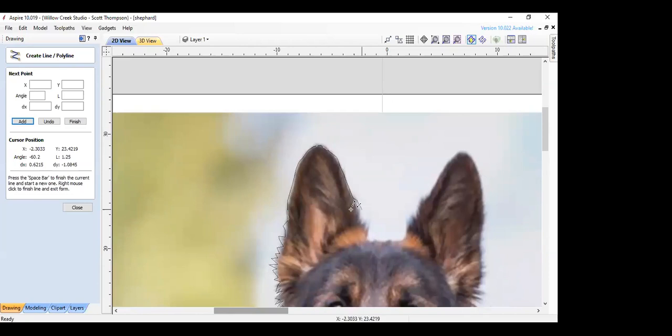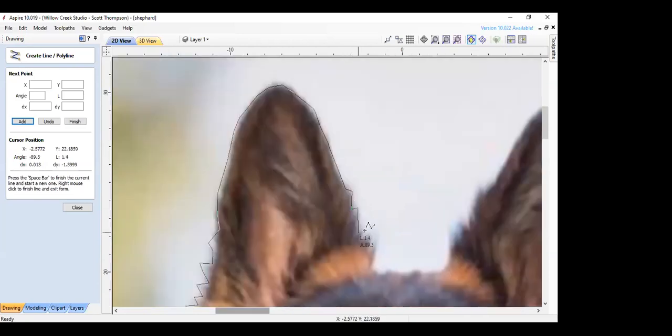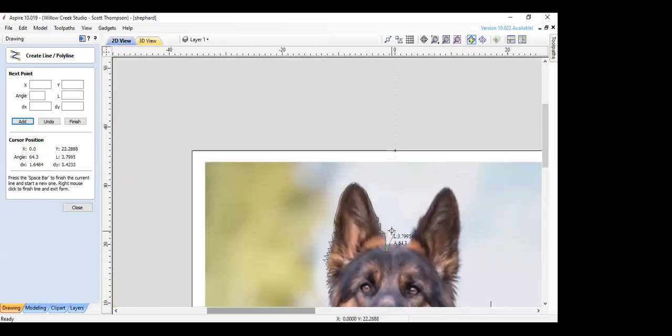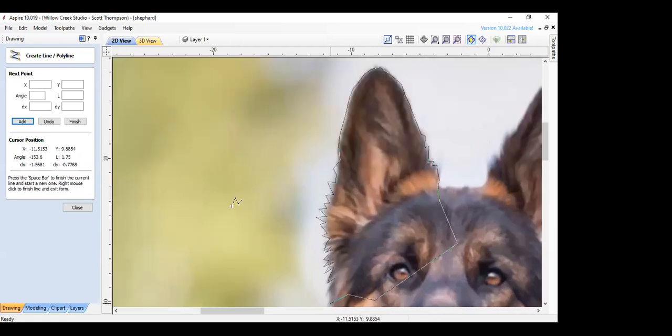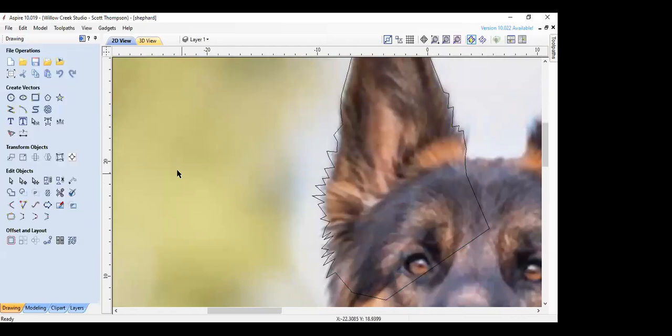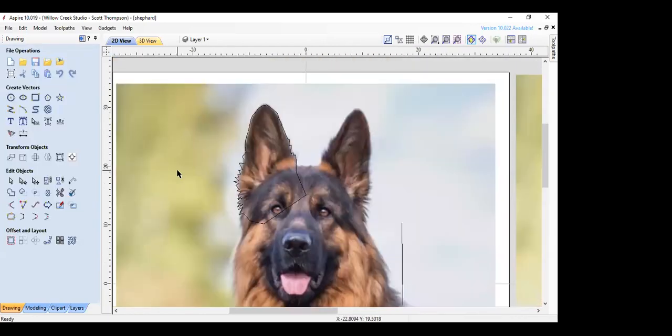So we're going to create a model of this ear at some point. Excuse me. And it's going to have some depth to it. So I'm going to come down here far enough into the head that I don't worry about losing part of the model, and it'll make more sense. Now I'll come back up here and click on toggle geometry, because I want these two ends to connect. So I've now made one element of that dog, and it's ready to start modeling that one ear.